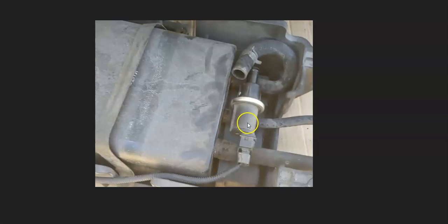because it's the main thing this code is pointing at. And once you locate it, the next thing to do is to examine all this wiring, because any bad wiring, open, short, anything like this is going to cause the same issues as a bad vent valve. So you're going to want to check that out really good.